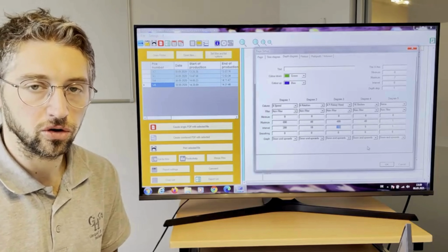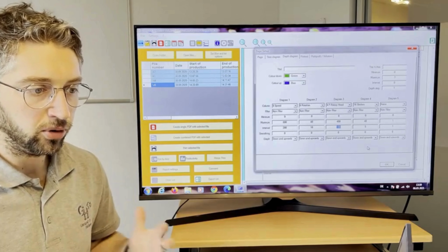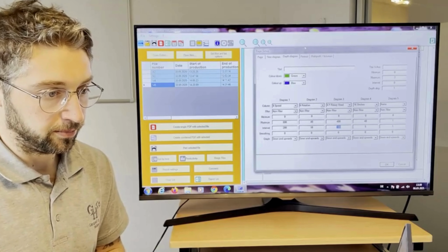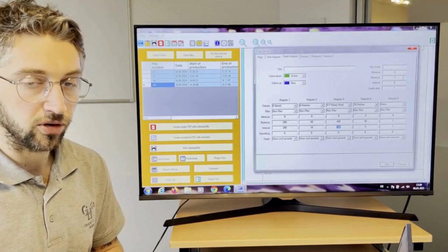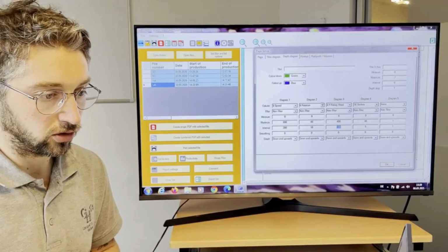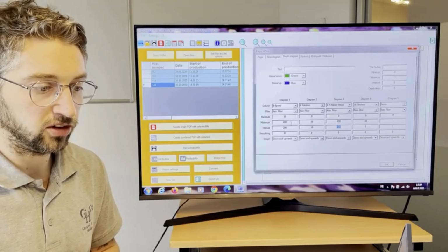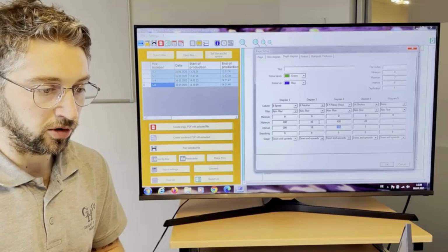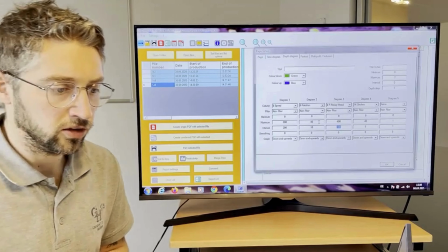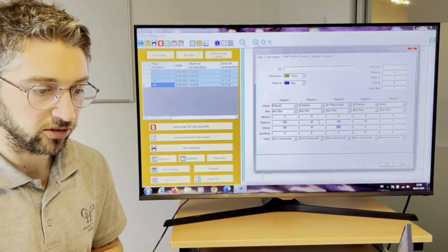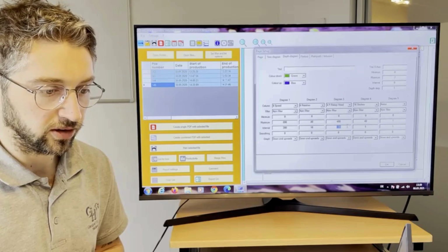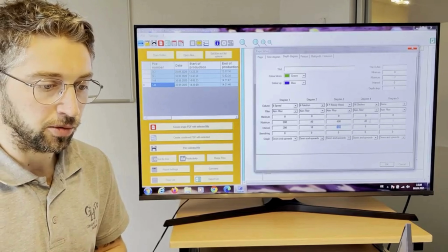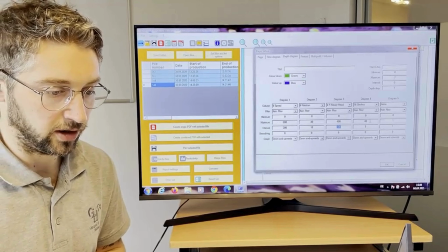So the next thing I want to show you is the depth diagram. I preset the values for this video to maximum depths of, again, -7. I choose the speed with a maximum of 800 and an interval of 200. The rotation of a maximum of 40 and an interval of 10. The rotary head pressure via the depths with a maximum of 400 and an interval of 100. And the strokes, again, with a maximum of 40 and an interval of 5.